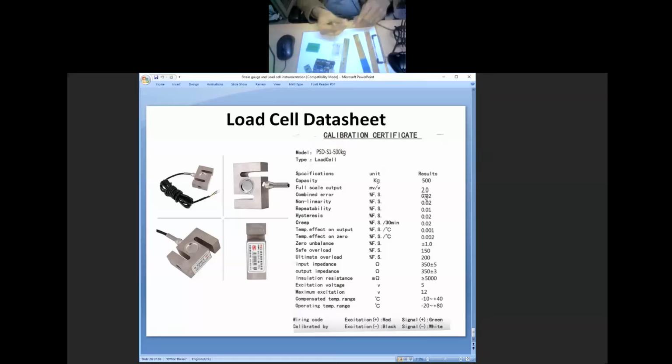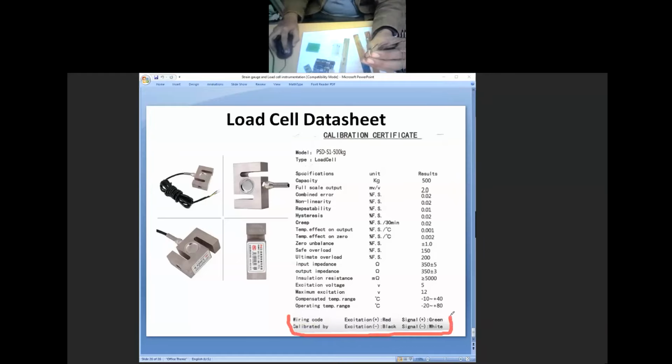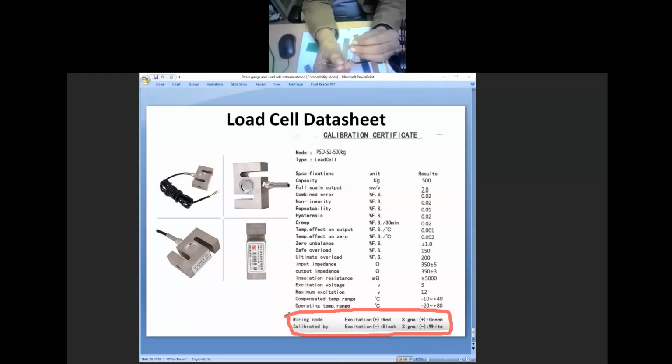Oh, I have not shown you the connection wires. If you can see here, remember, look at here. In every load cell, you have this. Don't forget, this is the most important thing. The connection diagram. So red and black, these are for excitation always. White and green, these are for signal, to take the signal out. This is the input, this is the output, and finally, this is for shielding. We always use shielding in every measurement. Otherwise, lots of noise comes. So we have 5 wires, 2 for input, 2 for excitation, 2 for output, 1 for common terminal or grounding purposes to eliminate noise.